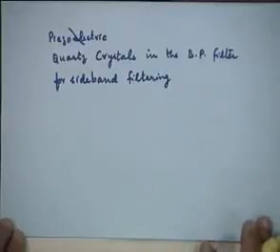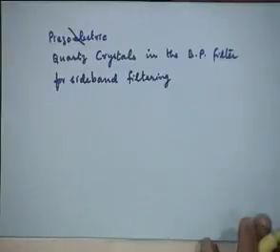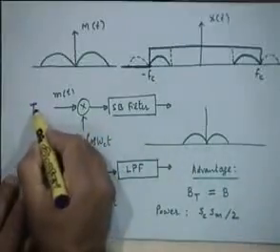Yes, please. So you said that using the single sideband modulation, we can actually reduce the bandwidth, as in terms of 2B to 1B. Right. So, but the thing is, we still are transmitting in that region. We just are removing it at the receiver via a filter. No. This sideband filter is at the transmitter. This is the transmitter.